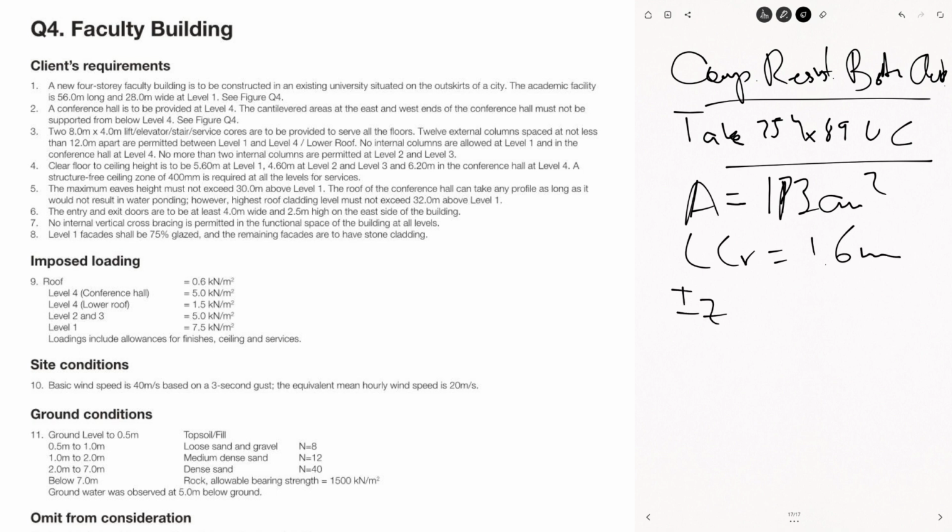The inertia, not the inertia. I'll need the inertia, but I'm following my template, so the radius of gyration is 6.55 centimeters, and my inertia now is 14300.